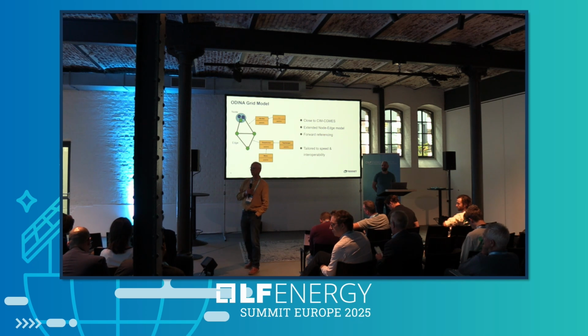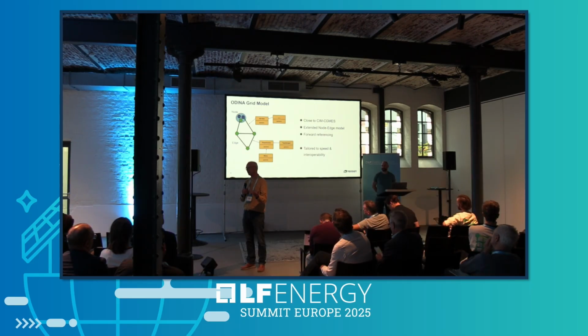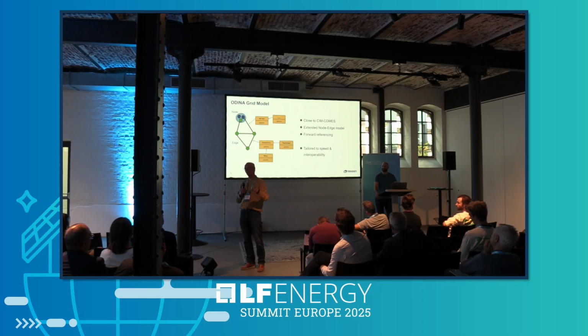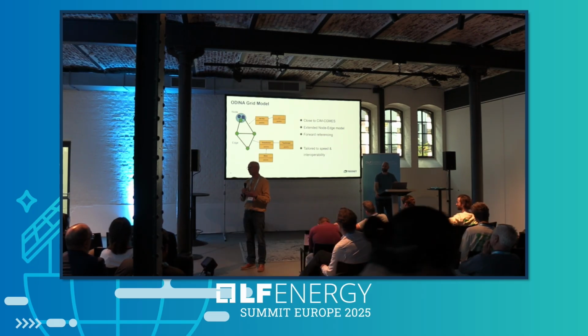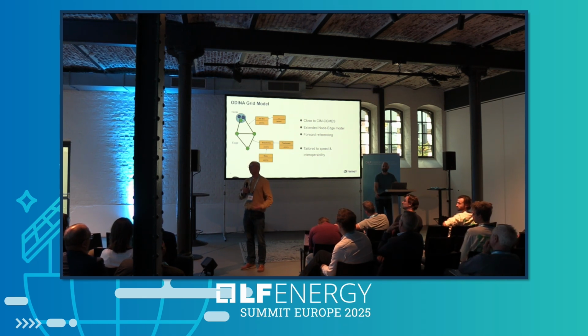Yeah, sure. Interoperability is a big thing, so we want to be as interoperable as possible, being able to import and export. At the moment we use PowerFactory, because that is the network model data that we have in TenneT. But we also export to PowerFactory. So we can import a model, do calculations, and then for specific hours, export those situations so they can be further analyzed with short circuit analysis or harmonics or dynamics or whatever. That is what we are doing at the moment. In the future, probably, we will change that to CGMES and export the results also in CGMES.